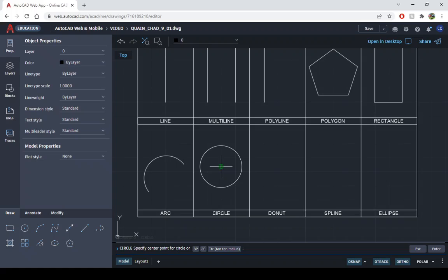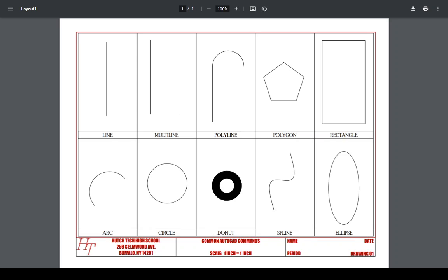I'm going to share this center circle here. I am going to scoot over here and draw one circle that has a diameter. You'll notice again I have a capital D, so that's my shortcut. So I can hit D, enter, 0.5. Now I want to get back into the same command again, so I'm going to hit the space bar. I'm going to pick the center point, go D, enter, 1, enter. Perfect.